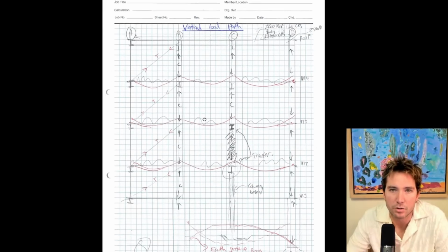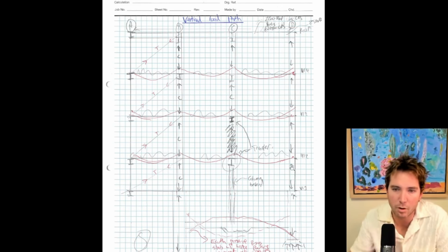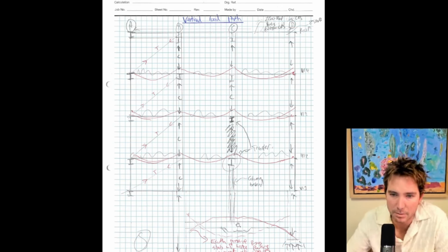Then here is my vertical load path. So as I mentioned before, I've got those diagonals that I'm using this time to avoid loading this existing sewer down here. That's my strategy there. My CLT spanning onto my beams and obviously columns, taking that down. I've got more columns in this scheme than scheme 1, so I will have a column coming down into my base slab, and I'm putting some thickenings here to account for that.